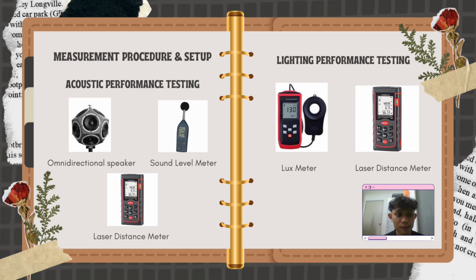So for light measurement, firstly, we use a lux meter and check all the lights. Next, we divide the hall. We split the hall into front, middle, and back sections. Next, we set the height. We held the lux meter at desk height, which is 1.2 meters, and point it up.